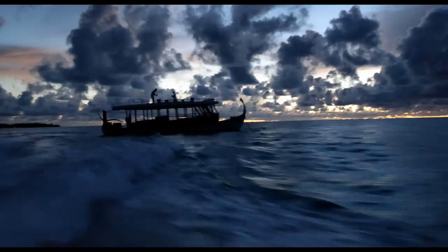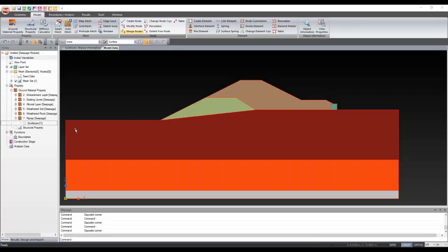And now what we do is we will directly run the analysis for seepage. For seepage analysis, we need to apply certain boundary conditions. So we will apply those boundary conditions now. The boundary conditions like total head and transient head, if you're having certain ones, we need to apply them now. What we need to do is mesh the model before applying any kind of nodal head or, let's say, transient head.